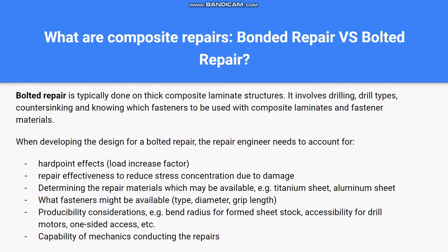What are composite repairs? Comparing bonded repair versus bolted repair. Bolted repair is typically done on thick composite laminate structures. It involves drilling, drill types, countersinking, and knowing which fasteners to be used with composite laminates and fastener materials.